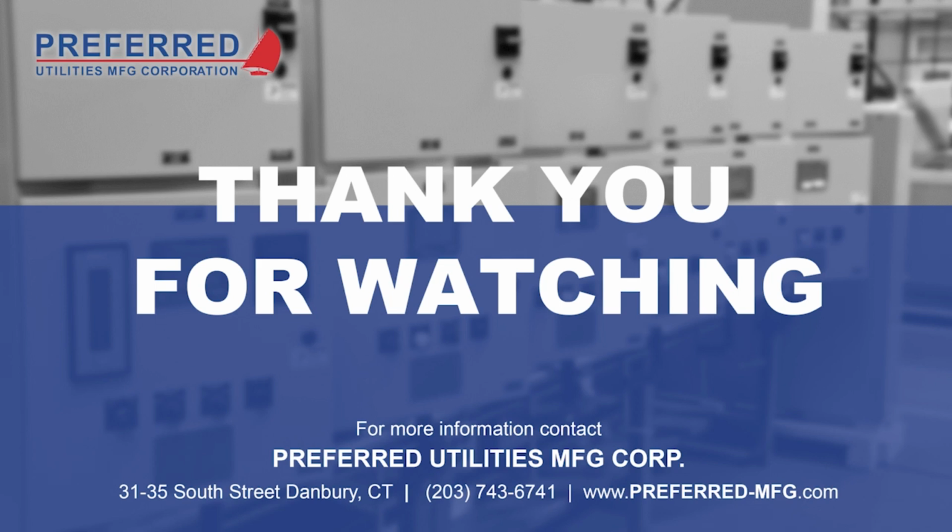Most flame safeguards will look for flame at the end of the PTFI, so it gives that period of time. Although we could also end up with a situation where we get a false flame where the spark is being picked up, and that's where we might want to change to an early spark termination flame safeguard setting.